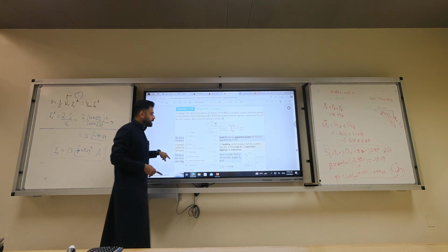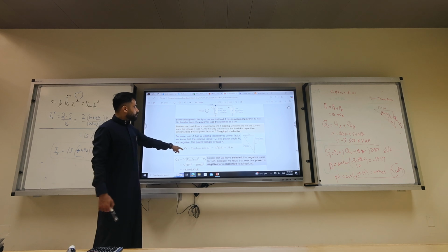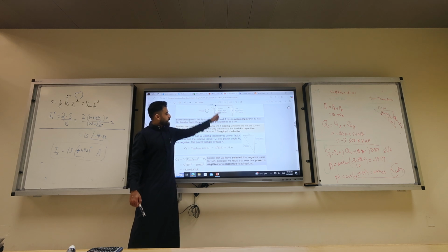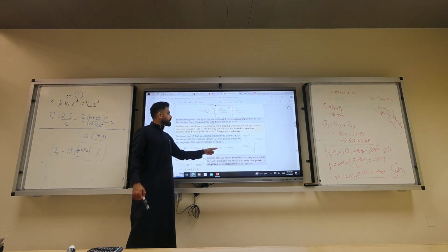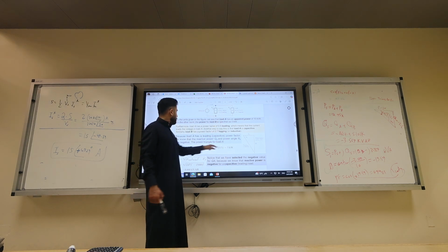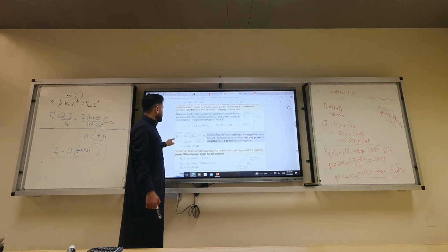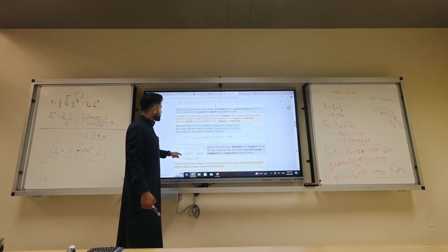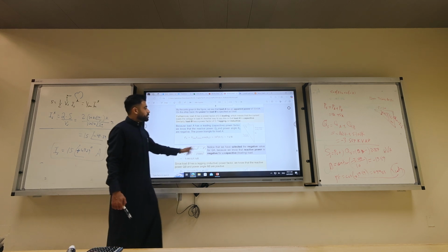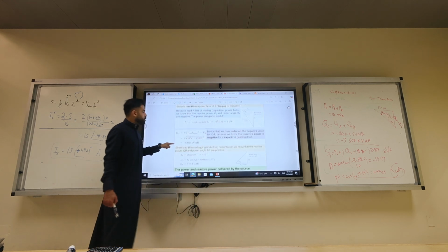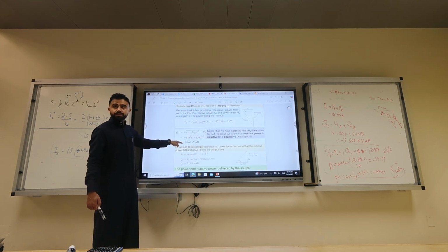From geometry, I can calculate P sub A, which is VAIA RMS, which is 10K, which is 10 to the power 4, times cosine theta, which is 0.5. So now I know P. Q is calculated by Pythagoras theorem, which is the square root of the apparent power squared minus the real power squared, which is going to be a negative number.